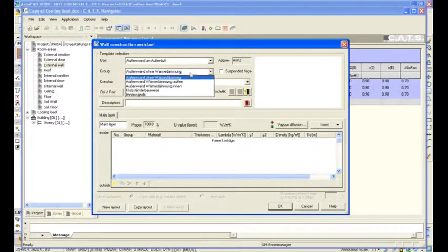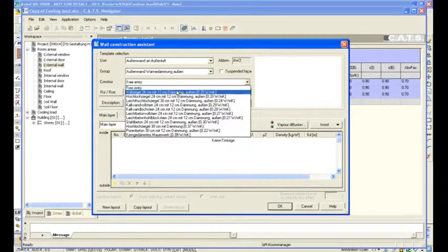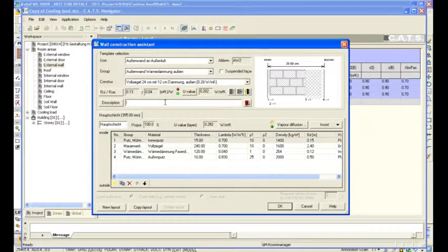You are able to select your walls from the database, or you may create your own specifications. We will select a block wall, stucco finish on both sides, along with its insulation and the insulation value. The U factor of the wall is determined by the section. Layer 1 is interior stucco, Layer 2 is concrete block, and Layer 3 is insulation board, including vapor barrier and stucco for Layer 4.